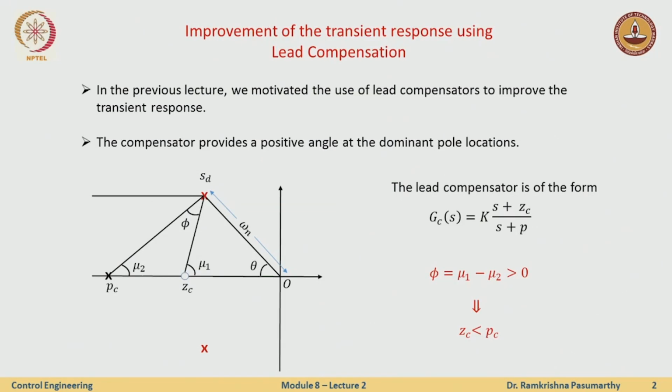Right. So what we concluded from the previous lecture is that this is the compensating zero and I should have a pole for practical reasons to realize this. And we also knew why the pole should be to the left of the zero. Right. So what we will now try to answer is where should the zero be and how far left should the pole be from the zero, and that will actually lead to some nice exciting observations.